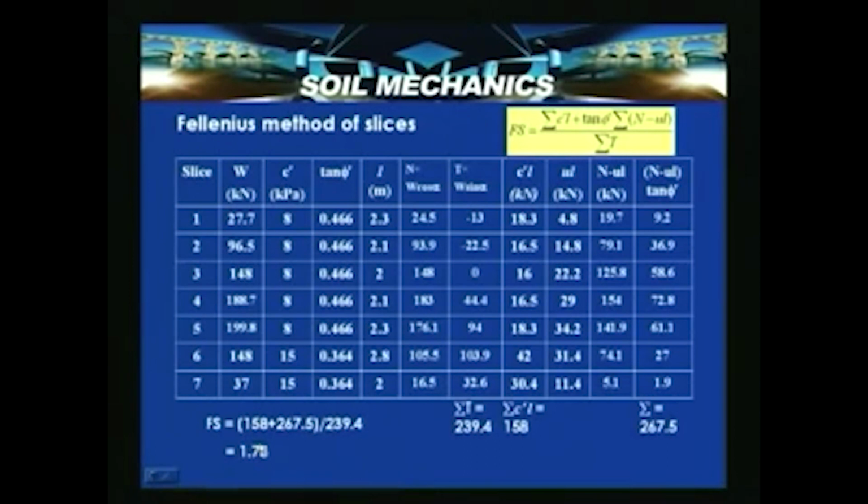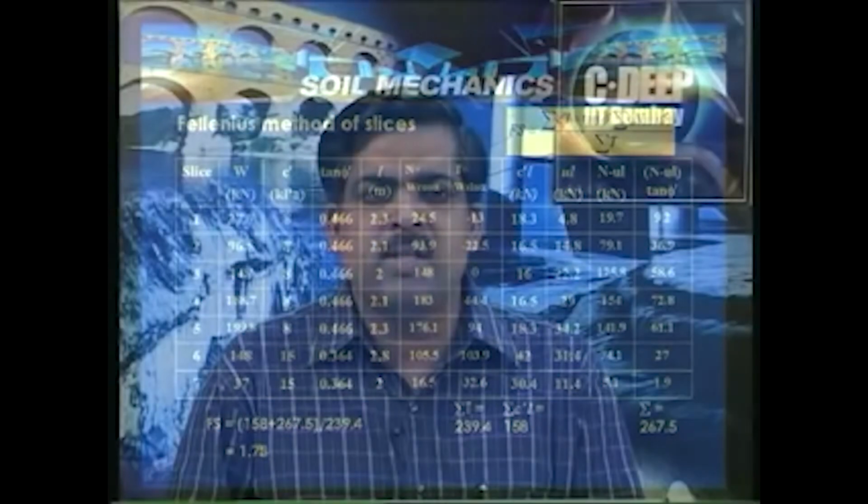A factor of safety equal to 1 indicates that the slope is on the verge of failure, but the convention for static loading conditions, the factor of safety which is adopted nominally for working stress conditions is about 1.5. If you consider the 3-dimensional effect of a slope, according to the DIN code, it is about 1.4. But there are different loading conditions like earthquake loading and other conditions that demand different factors of safety, but conventionally a factor of safety of 1.5 is adopted under working stress conditions.